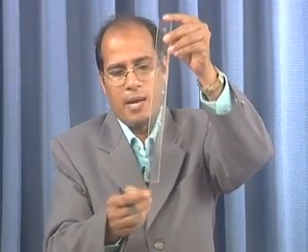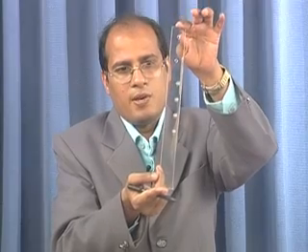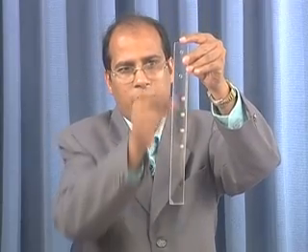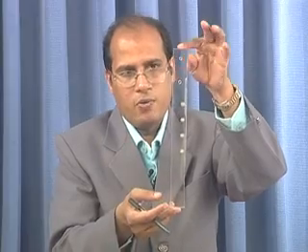In this case the vibration will take place in the longitudinal direction. So, in this longitudinal direction the wave propagation will take place in a cosine way. So, this phi n equal to a n cos n pi x by L.